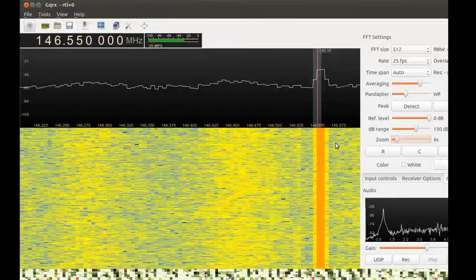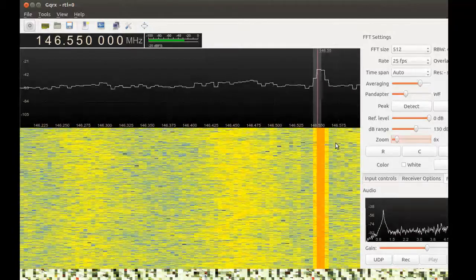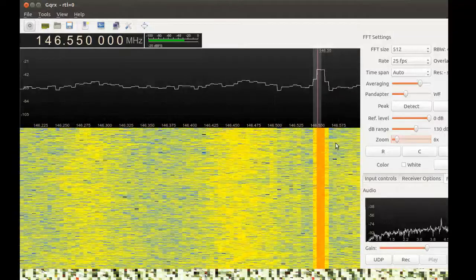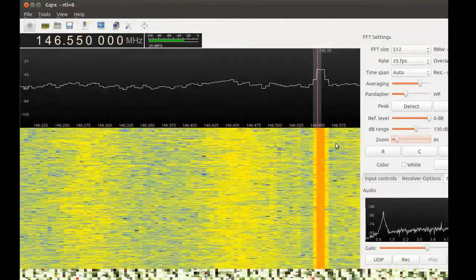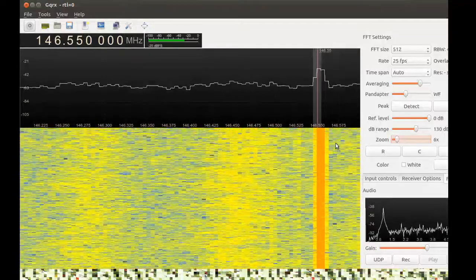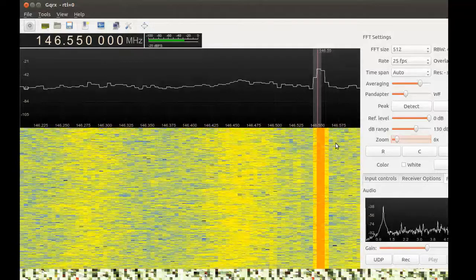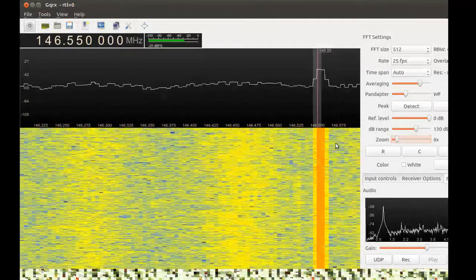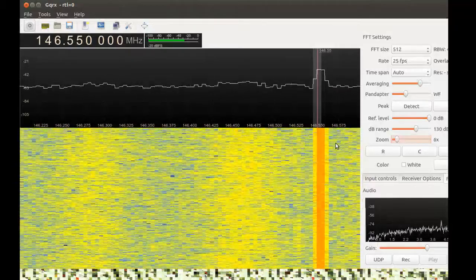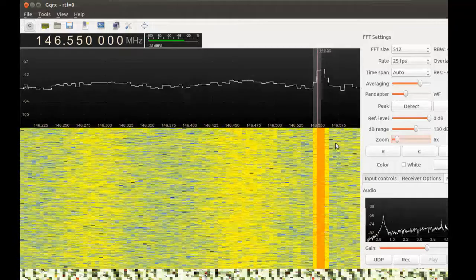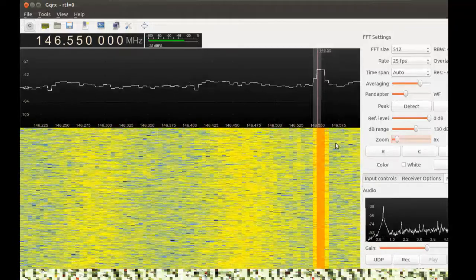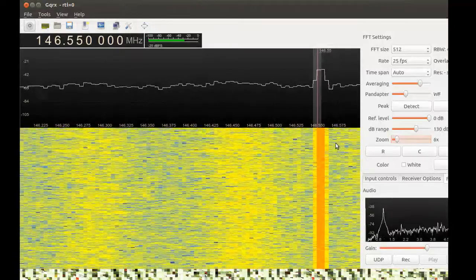Your SDR is plugged into the antenna. Yeah, that's the biggest suspect. Last week I had trouble with that connector. When I got home, I found the center pin had been pushed all the way back down. I pulled it back out with some needle nose. It seemed to work at the time, but check your antenna again. Not so much anymore. I diagnosed it last week because someone had a spare, just in case.